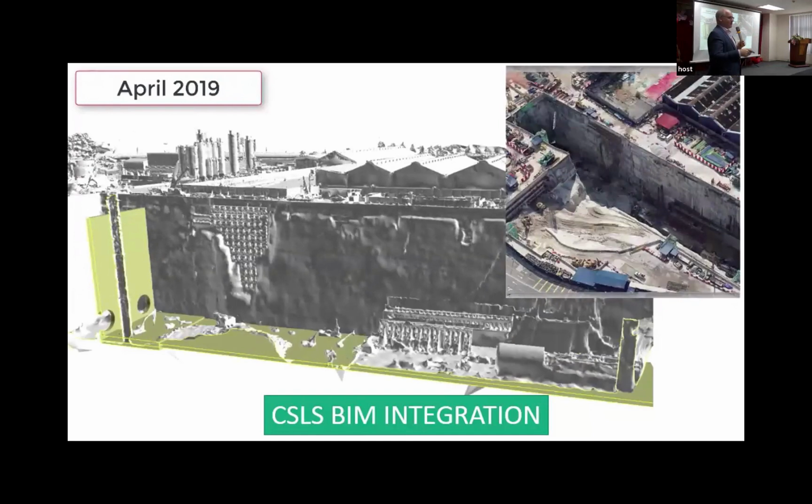The contractors who've done this now fly the drone every week, and they have an update every week of what's happening on the projects. So I'm not recommending it every week when you start off, but at a minimum, start once every month. But again, you need the model to get the value from the drones. So as you unlock BIM, as you get better at BIM, you can start to use these technologies to see what's happening on your site and compare that to what's in your models. And then you start to get more value from the whole process.